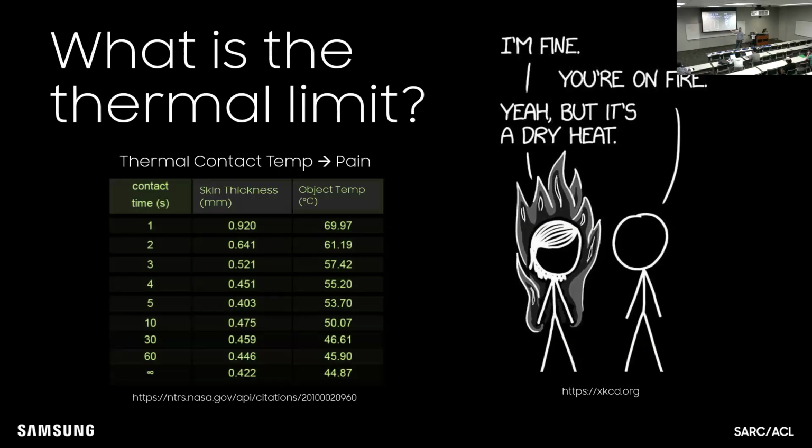And actually, that's one of the tests we have to run when we do something called DVFS, or dynamic voltage frequency scaling. We power back the phone to make sure that the thermals are always under 45 degrees C because you're holding it in your hand.